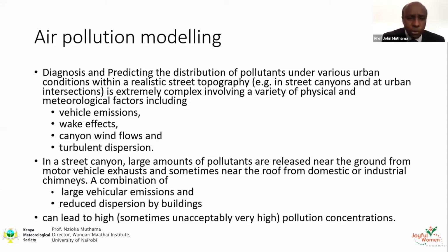Four of them. One of them is we must know the vehicular emissions. We must know the so-called wake effect. This is the circulation around a building, and also the canyon wind flow, the channeling of wind along certain streets. And then there's turbulence that comes in, and this becomes very important for us to do the modeling.